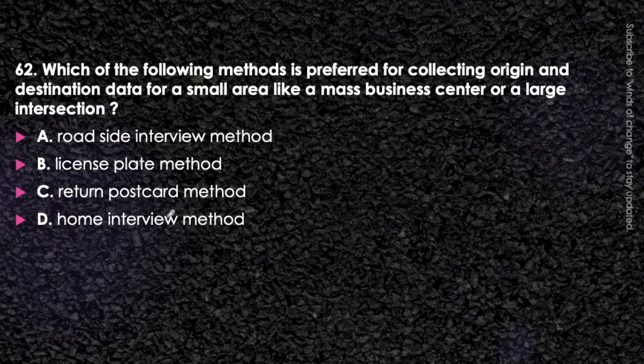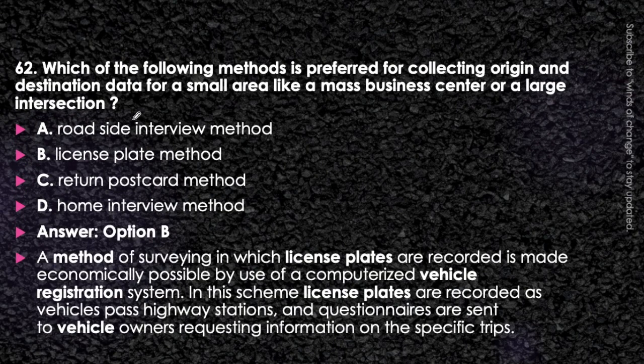Next question. Which of the following methods is preferred for collecting origin and destination data for a small area like a mass business center or a large intersection? Roadside interview method, license plate method, written postcard method or home interview method? Just think about it. It will be option B, the license plate method, which will be preferred in this case.